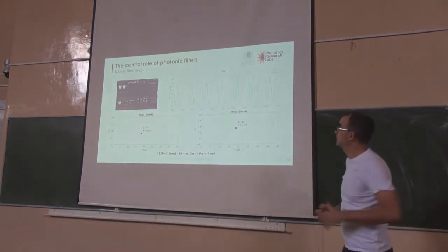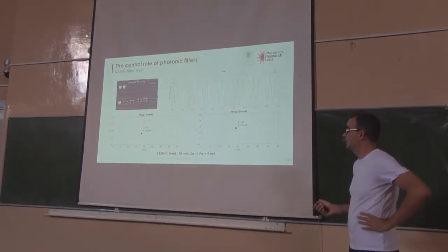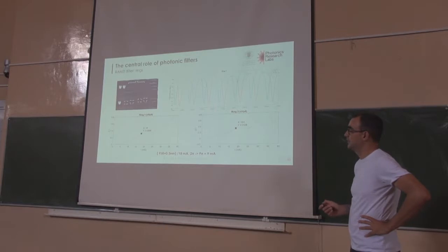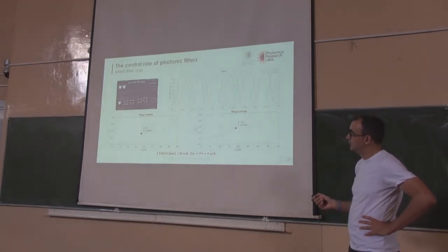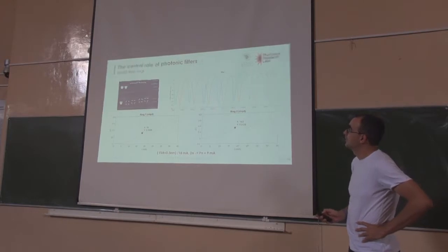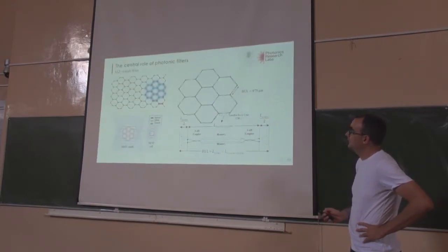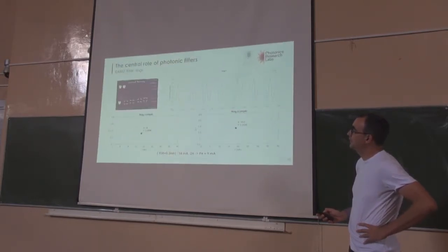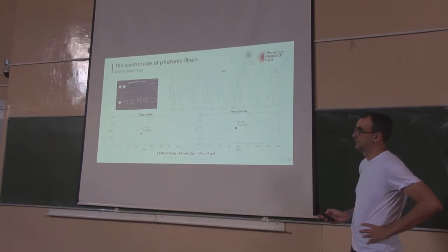Okay, these were measurements that we did a couple of weeks ago with some indium phosphide chips, and basically with 9 pi, it's equivalent, not equal, that is wrong, equivalent to a current injected of 9 milliamps. Okay. Then that was for the regular ring-assisted Mach-Zehnder filters.